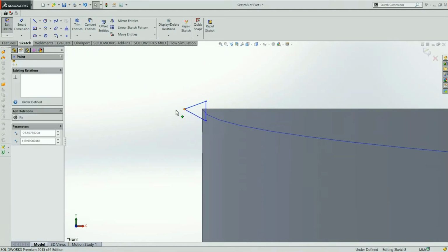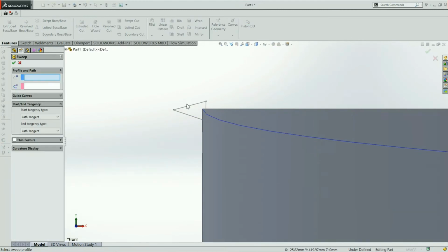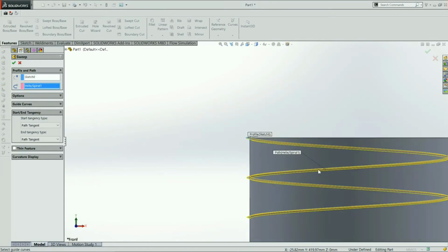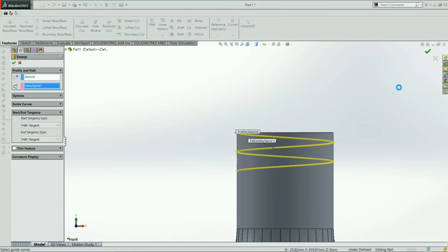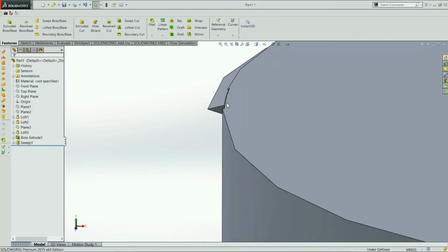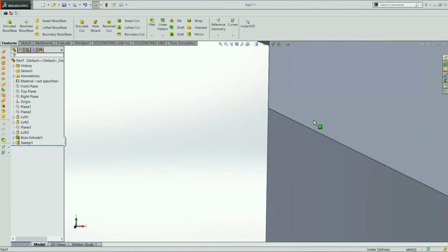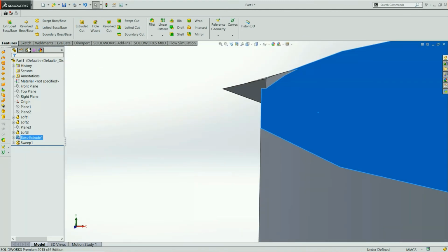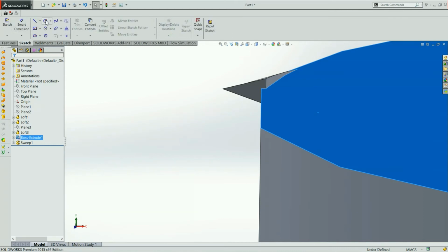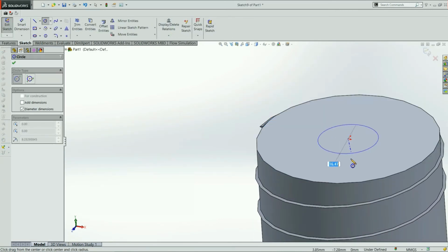I'm going to extend this peak part, and now let's give sweep. That's all, the thread is made. Now also here we could see that the part is somewhat made extending above the surface. To match this, I'm going to extend this part, taking perpendicular to this plane.